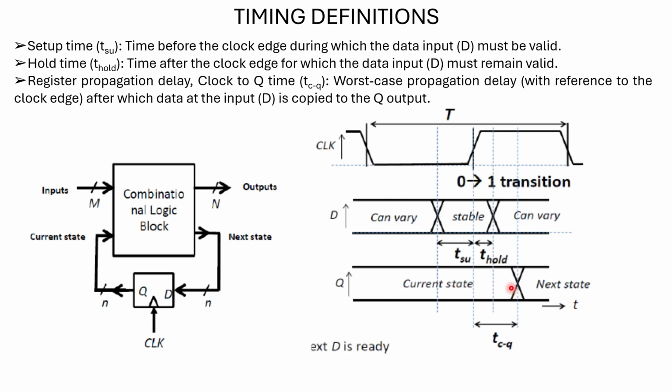So now there must be constraints. We have already said that, and there is also one more delay, which is called contamination delay. In combinational circuits, you have come across this term. Basically, you might know that the delay of a combinational circuit also depends upon the input patterns. Because of some input patterns, sometimes I will encounter less delay and sometimes more delay, and as a result there will exist some path on which there is the minimum delay, which is called the contamination delay.